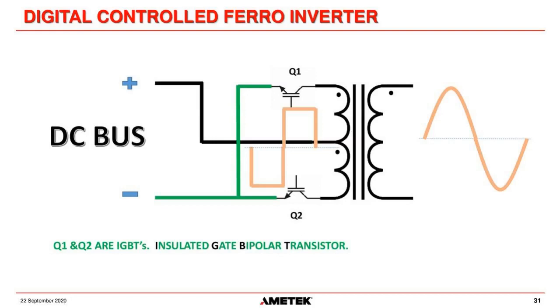Okay, so again, we use IGBTs, otherwise known as insulated gate bipolar transistor. And briefly, the IGBT is the closest thing we have today to the ideal switch for DC. Unlike an SCR, it only requires a little bit of power in milliamps to turn it on. And the great advantage is when you remove the drive signal, it shuts off. The SCRs have to be forced to turn off when they're switching DC. So it greatly reduces the inverter bridge.